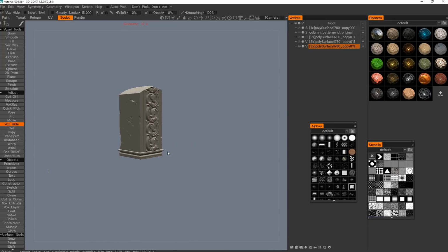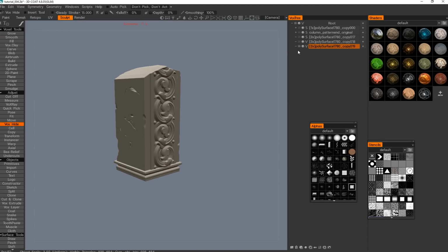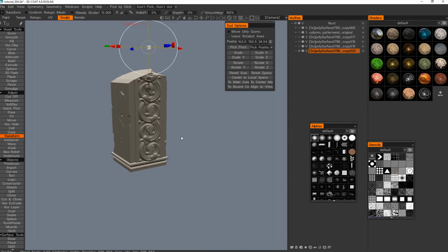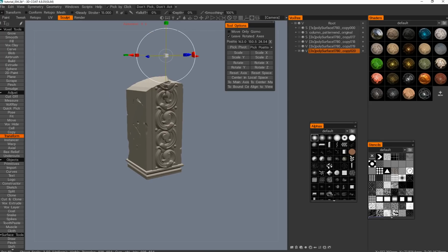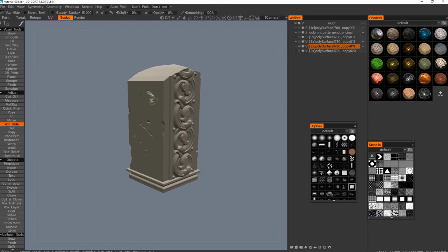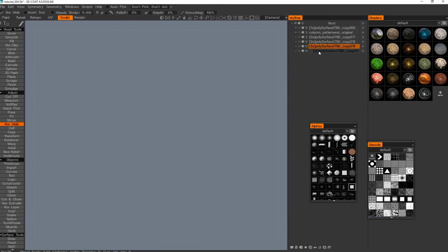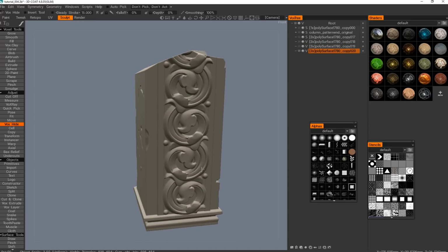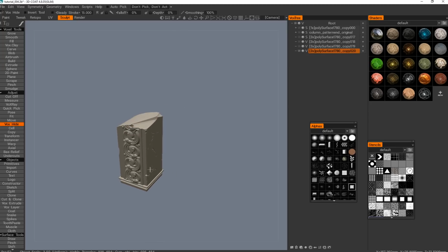Alright, so I'm happy with this part. Just duplicate it. Every time you duplicate, you delete everything, so all your box height has now been deleted and I cannot really unhide anything, while my original copy still has the box height. It's like duplication and killing all the changes, essentially destroying the history. So what I want to do is